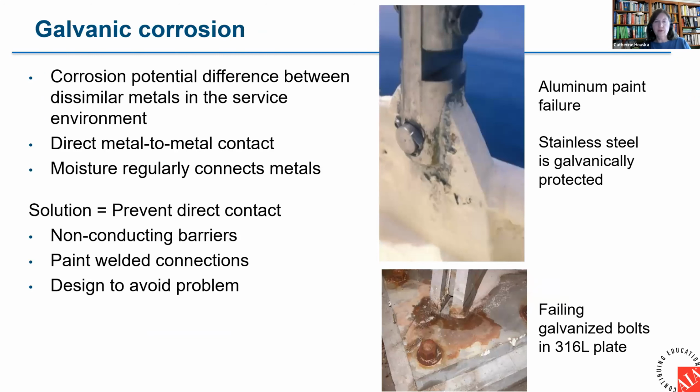Galvanic corrosion also has to be considered. It will not be the stainless steel that corrodes. It will be the aluminum or carbon steel that you connected it to. And surface area ratio plays a role in this too. If you have a large surface area of stainless steel and you've chosen to support it with aluminum or carbon steel, and there's no separation, then that aluminum or carbon steel will corrode at a highly accelerated rate, and both are already less corrosion resistant than stainless steel.